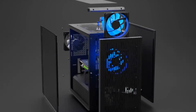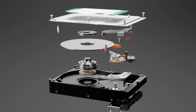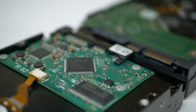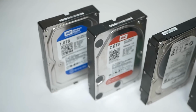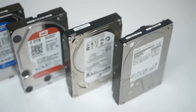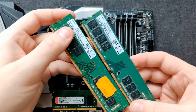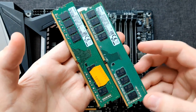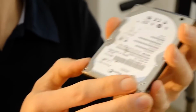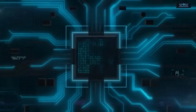Hard disk drives have impressive data storage density at a relatively low cost and also serve as non-volatile memory, meaning that the data written on them is preserved even after power is turned off. However, they also have their drawbacks. The key one is speed. While even relatively slow DRAM provides data transfer speeds of around 5,000 megabits per second, hard disk drives offer about 100 megabits per second, which is roughly 50 times slower than DRAM, not to mention the faster SRAM.